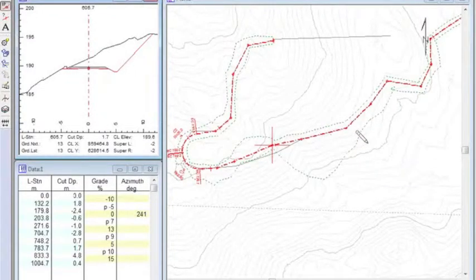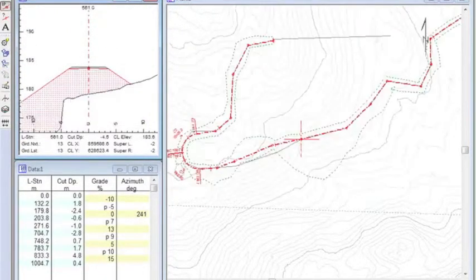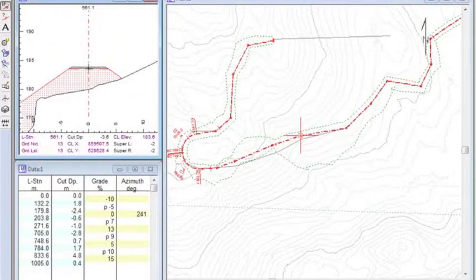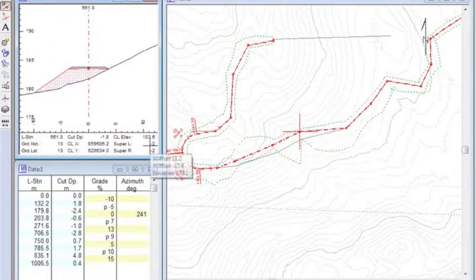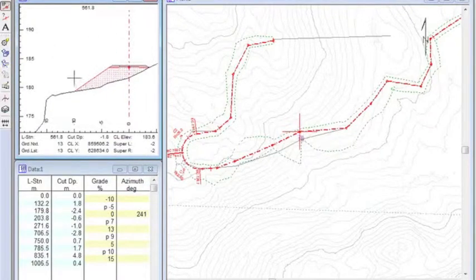Great. Now, I'm just going to move ahead, back actually, until I get to another horizontal alignment point, that one right there, to the plan window and move it over. Keep moving it over, not the plan, the section window, until, there you go. Now we've got not full bench, but at least we're not falling off the cliff there.